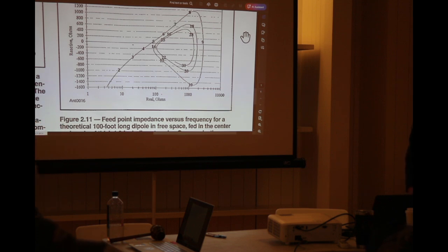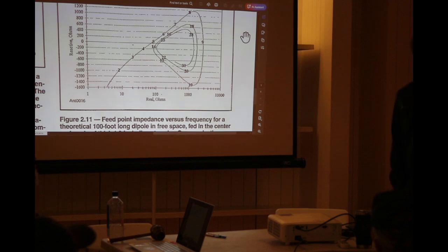The quarter wavelength Q section, again, is 100 years old, and they didn't have the math to describe it. But the guys putting the Zepp antennas on Zeppelins, the main purpose of which was to keep a wire a reasonable distance away from a gas bag the size of Milwaukee, used the quarter wavelength transmission line to convert the very high impedance at the end of the dipoles to a reasonable impedance for the antenna tuner.